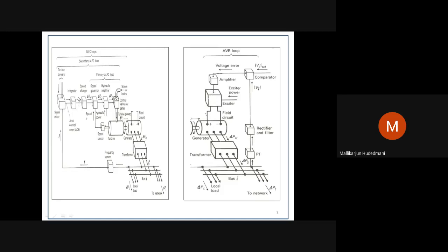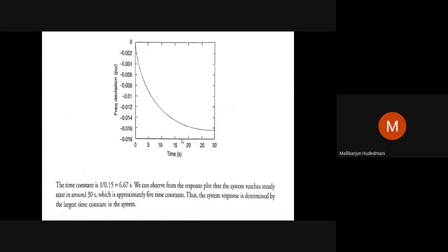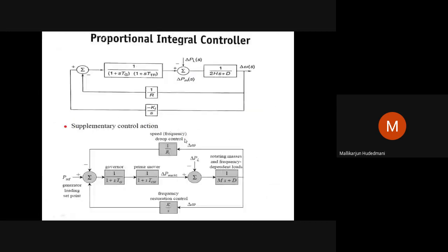When the set points are changed, the primary loop again accelerates. In this way, the supplementary loop has come into the picture. The supplementary loop is very necessary whenever the primary part of the ALFC becomes unable to bring the frequency deviation to 0. For that, we have seen the use of an integral controller. So a proportional integral controller has become necessary to incorporate in the path.